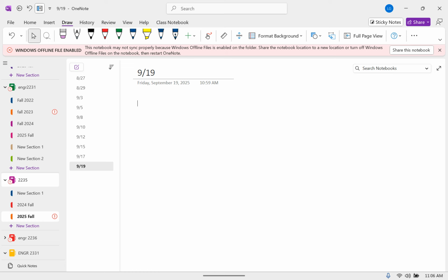How many total joint categories are there going to be in 2D? 3, yep, that's perfect. There are only 3 degrees of freedom, and that's all you can restrict. There will be 6 categories when we start doing 3-dimensional joints. Okay, so joint category 2.